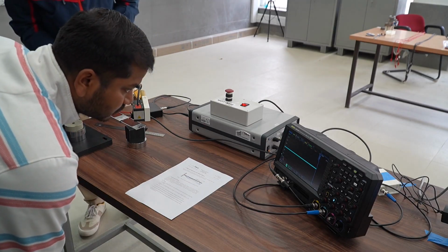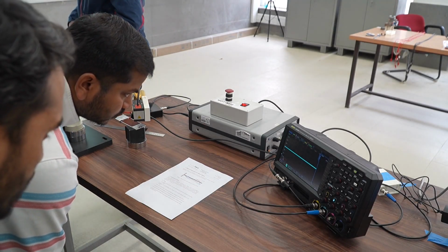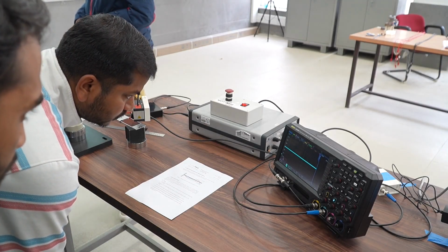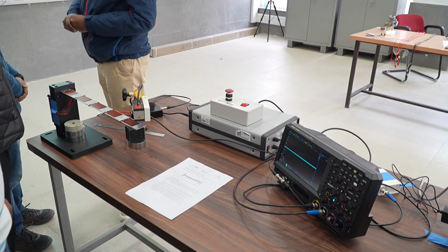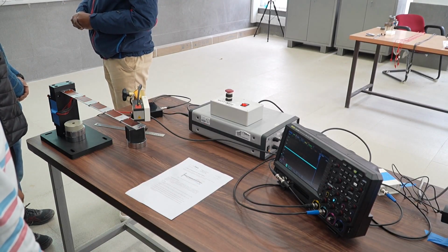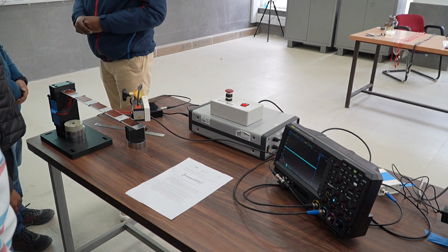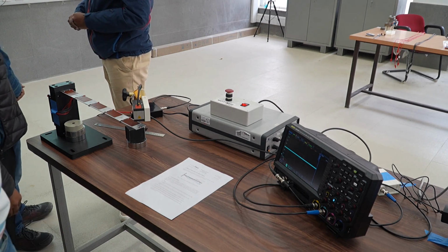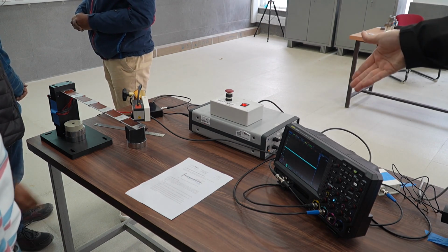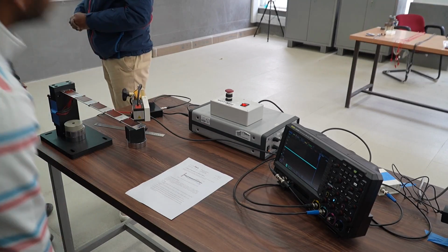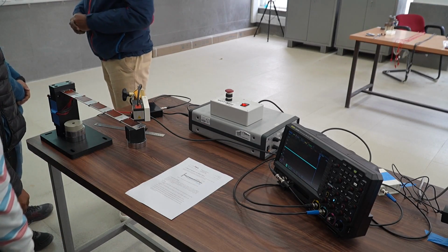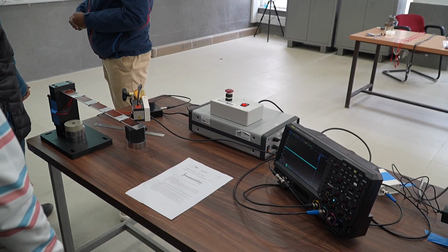No. 5 volt. The static state frequency. What is the static state frequency? 0. Yes, thank you. 0. Exactly. So you put in 0. And now you put in the maximum tip deflection at static state, which is? 5 volts. Yes, whatever, so more specific maybe. 4.98 volt.